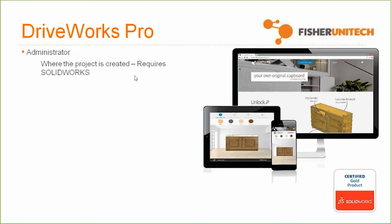If you're using a PDM solution from SolidWorks, you might already know that you can take inputs from data cards and have them push into various kinds of documents, whether it be a drawing sheet document or a Word document or a PowerPoint document. They all have an add-in that allows them to take inputs from PDM directly into those documents. Well, DriveWorks is very similar. Also, there's DriveWorks Autopilot. DriveWorks Autopilot is the piece of software that gets linked up with DriveWorks Professional that allows you to automatically generate your models. Without Autopilot, you have to open up SolidWorks in order to generate your models.